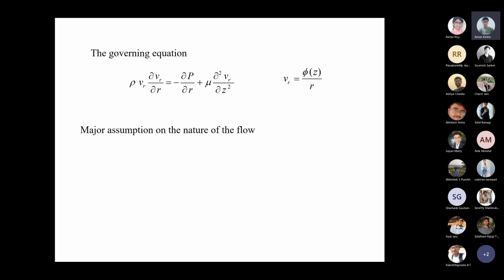What kind of momentum transport are we expressing by the terms which appear on the left hand side? Convective transport, conductive transport, or something else? Convective. And your reason for making that statement? It's VR, so it's in the direction of r, and we are seeing that it's changing with the direction of r. Perfect.